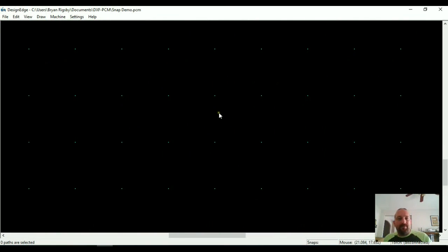For grid, I'm going to zoom way in so you can see that, and I'm going to G snap first, and that's going to get me right on that point. If I G snap again, you can see now that I'm limited. I can move a quarter at a time. Every time I get past it, it jumps to there. So that's a half, 3/4, 1. And that's because I set that to a 1-inch grid with 4 snaps.